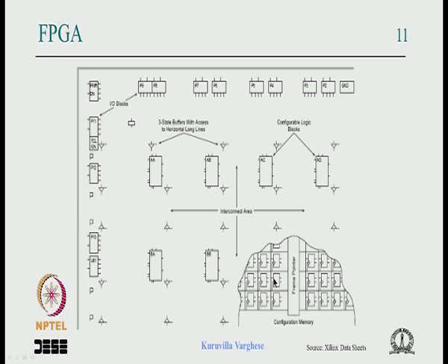Compared to a normal ASIC, this makes the FPGA quite big. Maybe it dissipates more power, so the raw speed of an FPGA may not be as high as, say, 1 gig or 2 gig. Maybe the serial transceivers go at high speed because that is easy to design, but a general lookup table speed may not be that high.